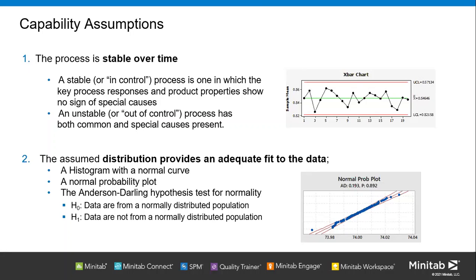If you face that kind of situation and then try to measure your CP, CPK, maybe something is wrong, and you should not rely on it, because you failed the first assumption. The second assumption is that you need to have a distribution inside your process itself, whether normal or non-normal. If you want to look at the normal capability, make sure that the process is normally distributed.